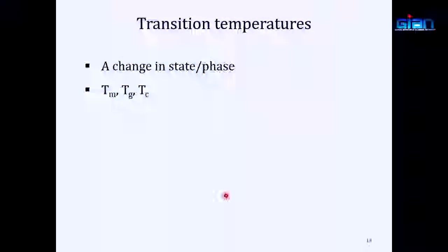So if you have a polymer which you are going to use for a thermal processing application, what would be the processing temperature? 121 degrees C, or sometimes even a few degrees higher, right? So you don't want this material at that temperature to go through state or phase transitions, right? Because if the package goes through a state or phase transition, then what will happen? With small pressure, it will have a deformation, right? So you don't want that. So that's why it is important.